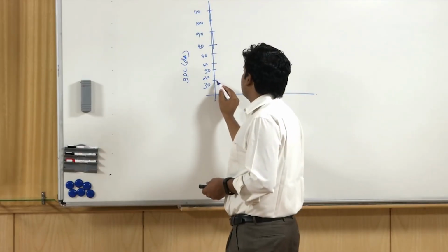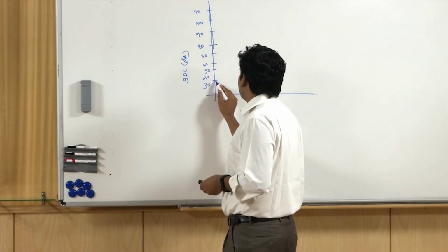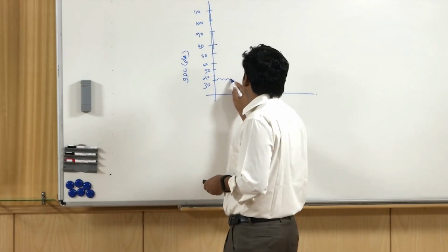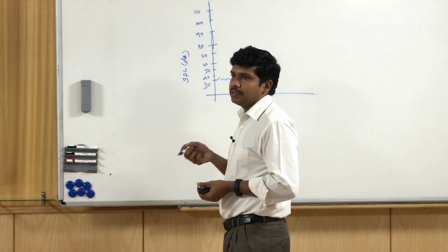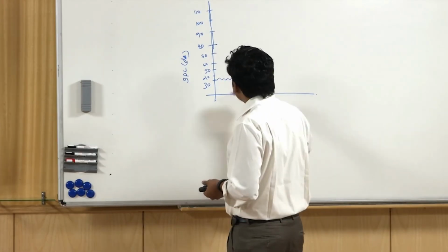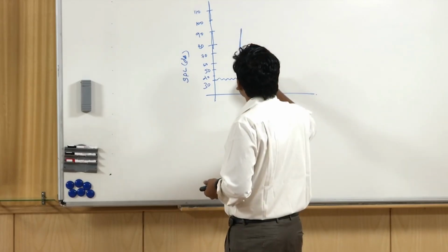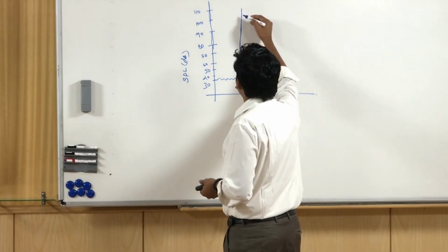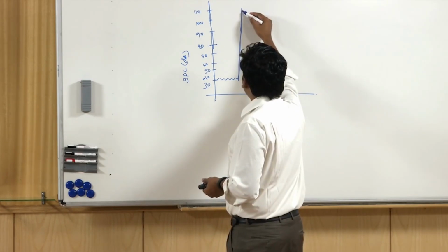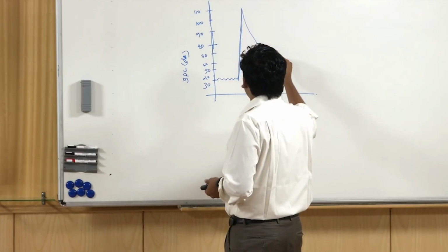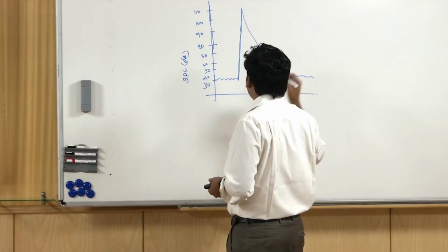Now there is a background noise level, like we looked at. Say it is a small lecture hall, you have a certain background noise level across the time. You are going to create an impulsive sound, say for example you are bursting a cracker. What would happen? There would be a sharp sound which goes as high as, for example, 110 dB, then it would not decay that fast, but it would eventually be decaying, there will be a slope and then after a while it would come back to the background noise level.